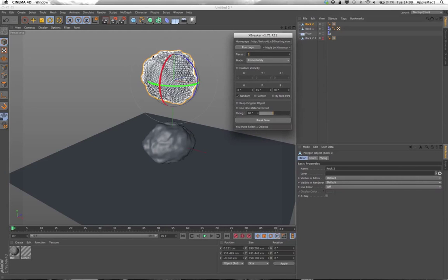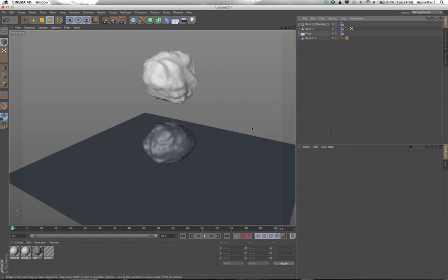The way these rocks have been created, I was looking at it earlier, and inputting numbers such as 15 really deforms the way the rock looks, and it doesn't look good at all. So through trial and error, 5 seems to be quite good. You can go further after that, but just go in small steps. So put 5 in there and click break now.